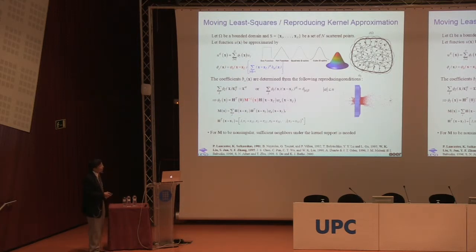Further, one can try to compromise on that. For example, if I just use a constant basis, I will have partition of unity, right? So that's a minimum requirement for convergence, and I know that will be fine. But it converges really slowly, because if it can only reproduce a constant field, that means the truncation error is first order. So it will converge, but really slowly, and that's also something that we don't want. So if you want sufficient accuracy, but at the same time want this moment matrix to always be non-singular, then you have to do something about it.